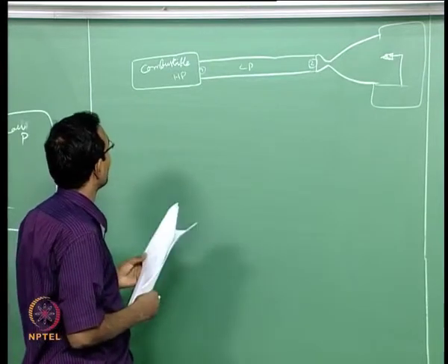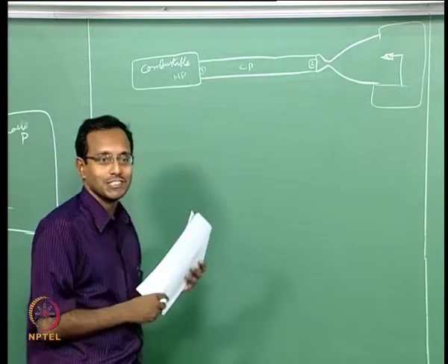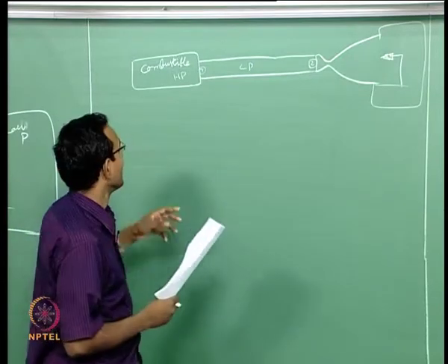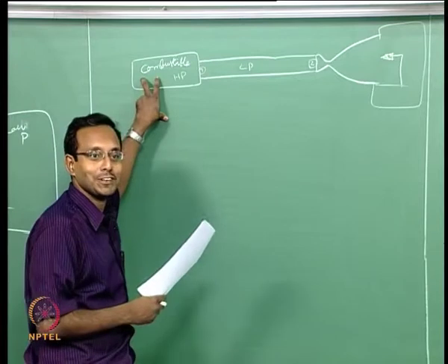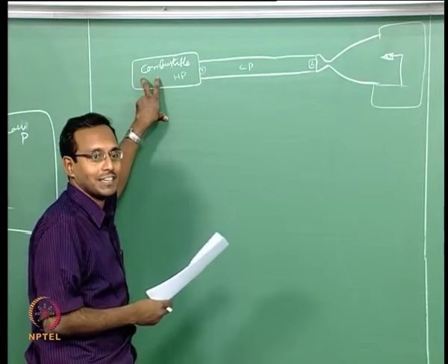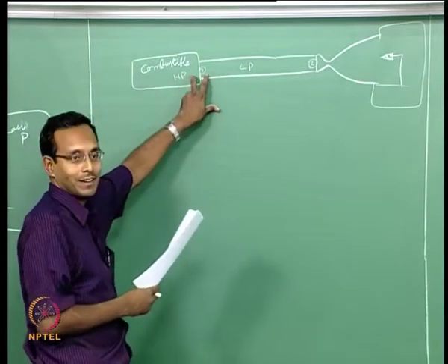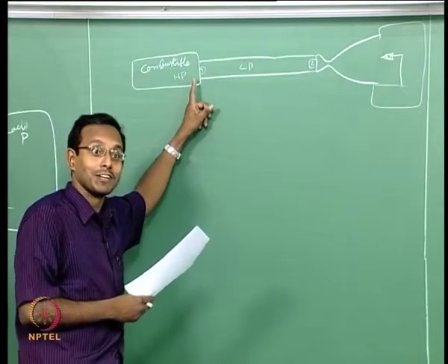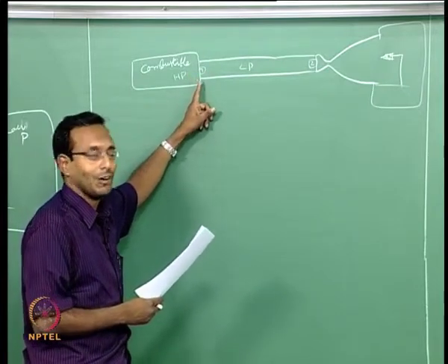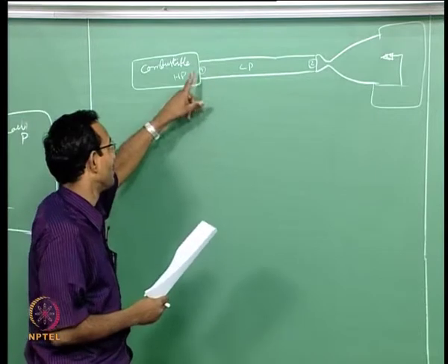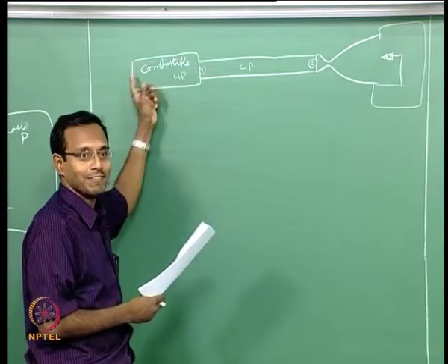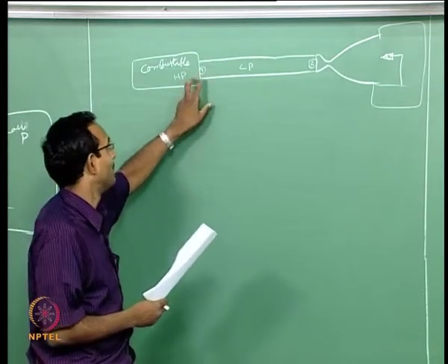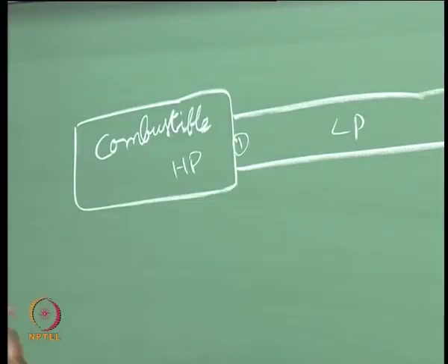But it is a little more complex. Now I have to think about, when I want to start this tunnel, have I created the correct mixture, is it really combustible, is it at the correct pressure so that the diaphragm will break, will the diaphragm break before the ignition happens. All that details I have to now think about. It should not break before the ignition happens, but it has to break after the ignition happens. So the diaphragm should be calibrated better.